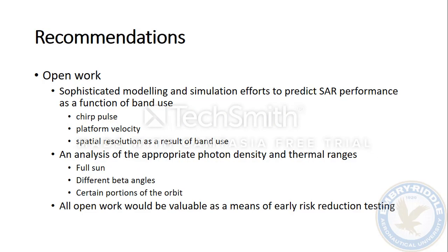So what are the recommendations? What are we going to do from here? Some of the open work that I recommend is those sophisticated modeling and simulation efforts to determine or predict SAR performance as a function of band use. So chirp pulse, the platform velocity, and then the spatial resolution as more of a function of band and all those other factors that we talked about before, going all the way back to the geometry of SAR and how it works.